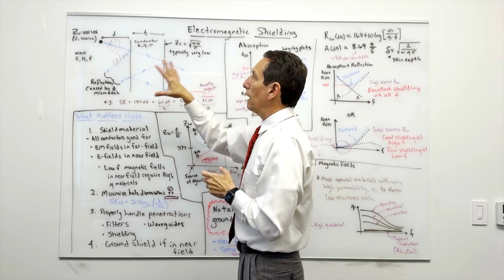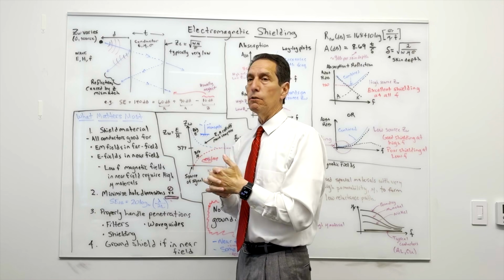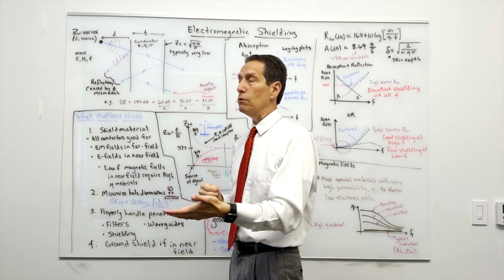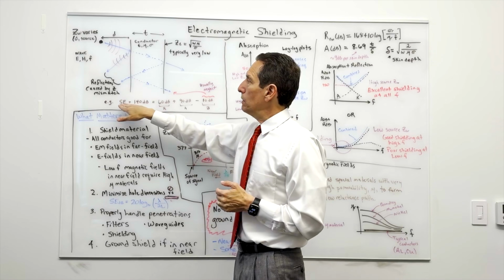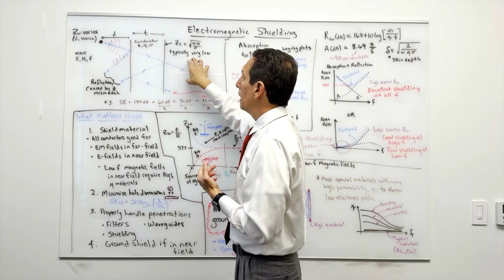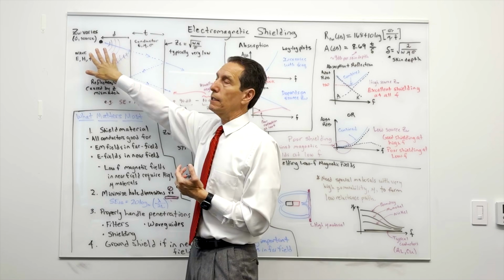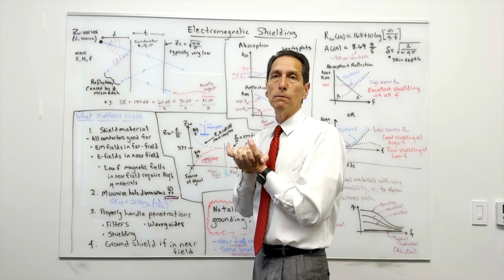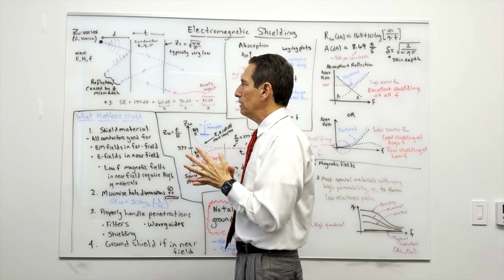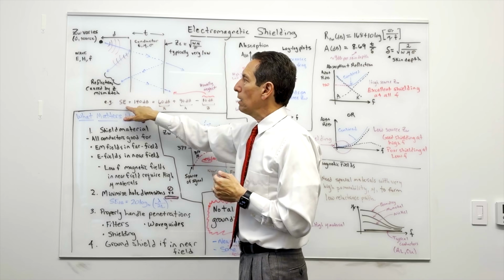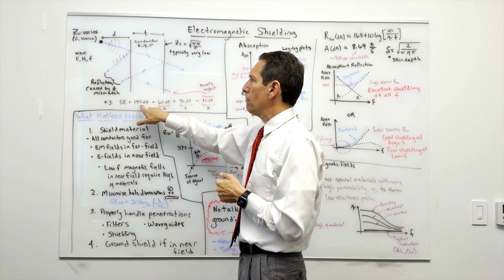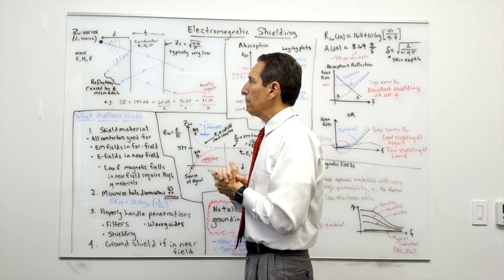And so we could calculate those things, and you can run them through simulators and determine how well a particular conductor acts as a shield, okay? So maybe when you calculate the shielding effectiveness, and again, that's really just a measure of what percentage is on the other side of the barrier from what came in, right? You want as small a percentage as possible, and you convert that to something called a decibel, which is just a logarithmic ratio, and you'll get some kind of shielding effectiveness. The higher, the better, okay? So let's say you had 140 dB, it might be made up of three components.